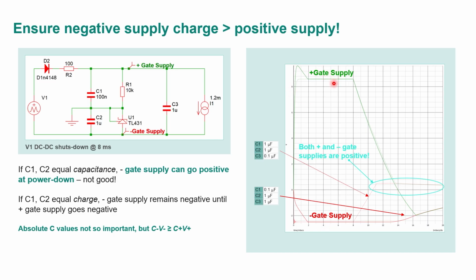Now you pull the plug, the power supply is powering down. What happens next? The RC decay, when I have the same value capacitors here, I get this behavior, and it's the same on the plus supply pretty much. This follows down here. You can see it's approaching 0, and then it even goes negative here.